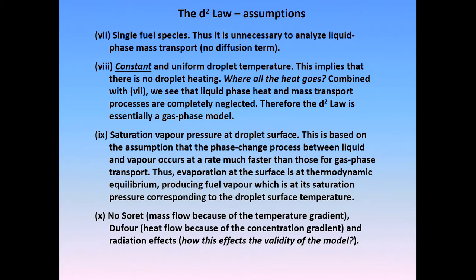Some of the additional assumptions are that you have to assume a single fuel species, or whatever species you are assuming, and a constant and uniform droplet surface temperature. That means there is no spatial variation of the droplet surface temperature, and there is no temporal variation of the droplet surface temperature as well. And it is basically a gas phase model, we will not do anything to the liquid phase.